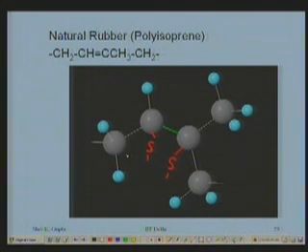Both of them may go to the same monomer, or both may not. They may go to different monomers of different chains. So there is a link, called a cross link, between this chain and another chain. The cross link is formed because the double bond breaks and two single bonds are formed, which are joined by sulfur. That's the role played by sulfur during the process of vulcanization.